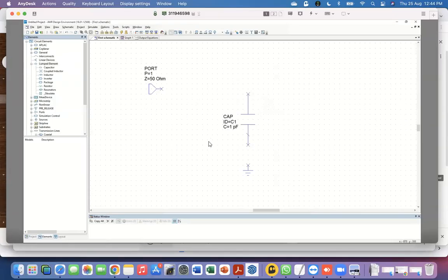Okay. So I'm going to now create a simple circuit. So I have taken a capacitor. So this was from here. So when I, under lumped element, I click capacitors. And under that, there's a whole bunch of things here. I will not go into this detail today, but you choose this one for the simplest case, which is this cap, which says capacitor closed form. There are other kinds of things. If you look at cap Q, and I will discuss where those things are used later on. They are basically small amount of non-idealities introduced into the model itself.